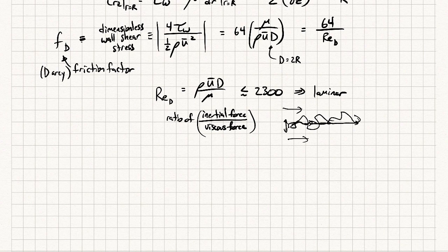So if you had a small Reynolds number, the perturbations will get damped out and it'll tend to flow just in layers. It'll be a laminar flow. Whereas a large Reynolds number will start to become more seemingly chaotic in behavior, and that becomes more of a turbulent flow. So that's a quick and dirty way to physically get a picture behind why smaller Reynolds numbers result in laminar flows.